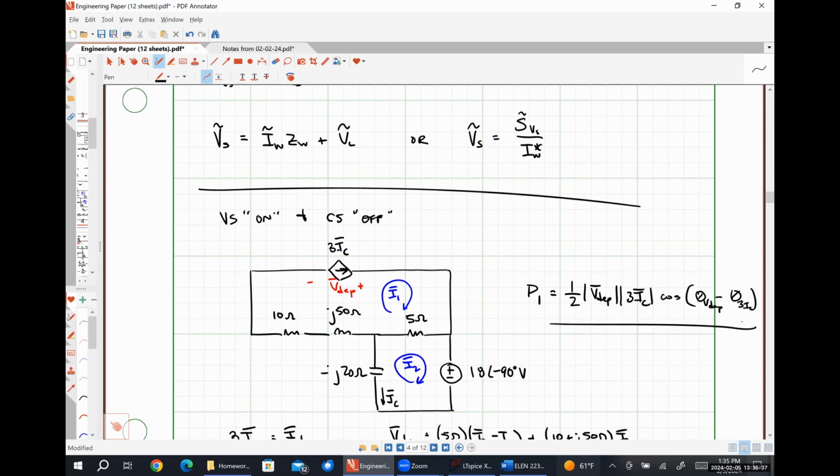All of the other parts are sinusoidally varying, and their average value is going to be 0. So it happens to work in AC circuits because of how multiplying sine functions works, and the average value of a sine function over an integer number of periods is always 0.